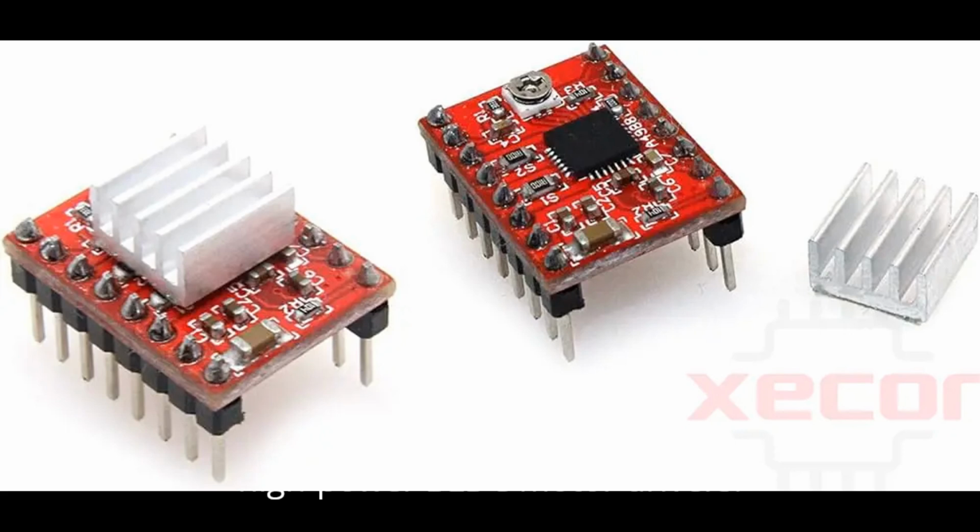7. High-power BLDC motor drivers. Function: these drivers are designed to handle higher currents and voltages, making them suitable for high-power applications. Operation: these drivers can control large BLDC motors typically found in electric vehicles, EVs, industrial machinery, and high-performance robotics. They use sophisticated algorithms, such as field-oriented control, FOC, to efficiently manage high-power motors. Advantages: high power output and robust performance for demanding applications.